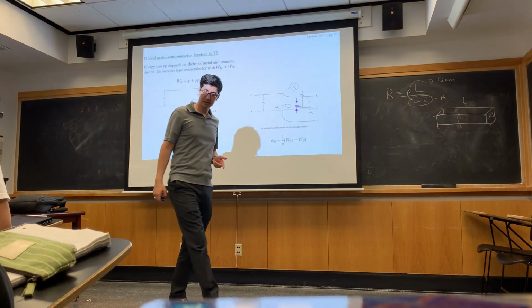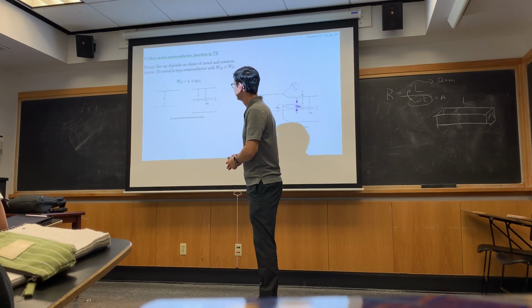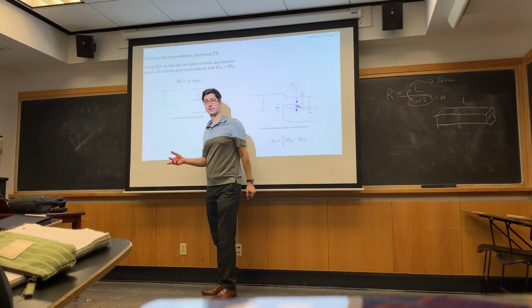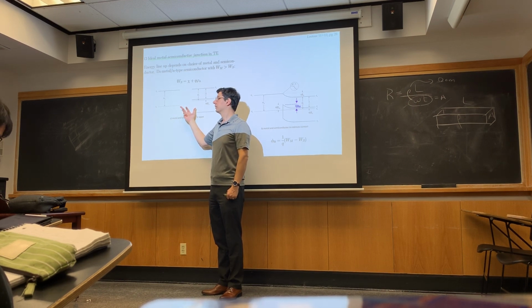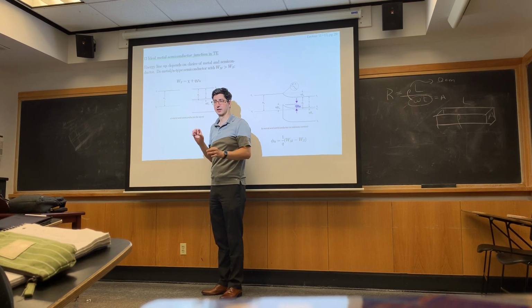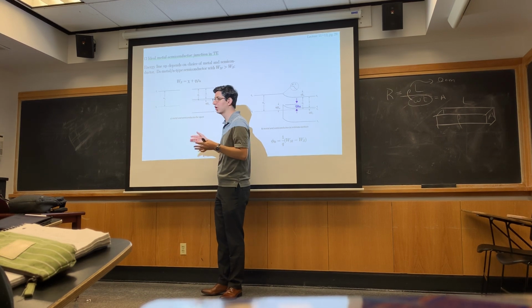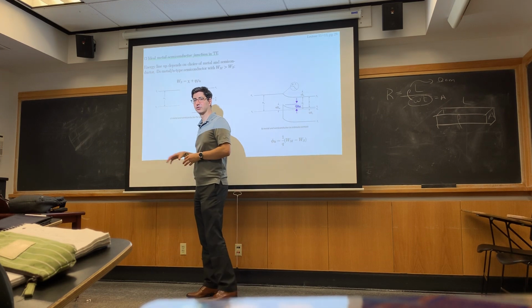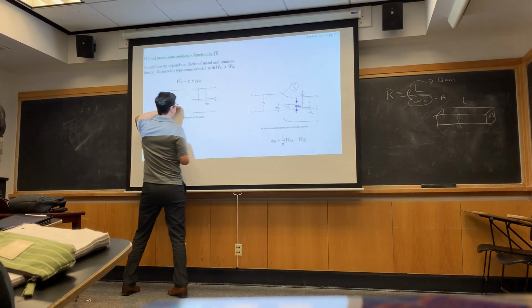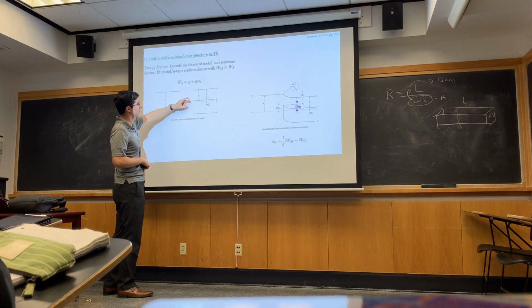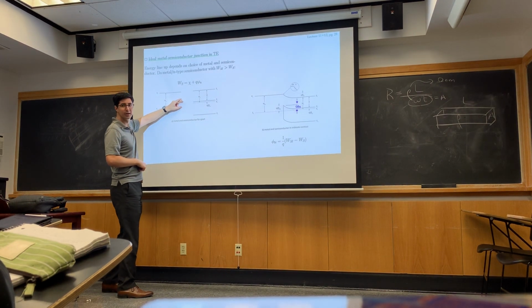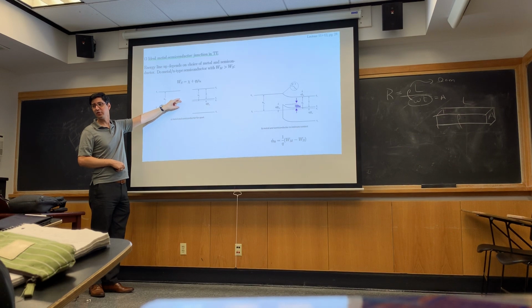This is a little bit different than a p-n junction, because if you like to think of it in such a way, it's a heterostructure. These are different materials. Hetero meaning different. The other ones you've looked at have been homostructures. It's just silicon-silicon, the same material. Yes, it's differently doped, but there are no discontinuities in the bands. This difference between EC and here is a material property.